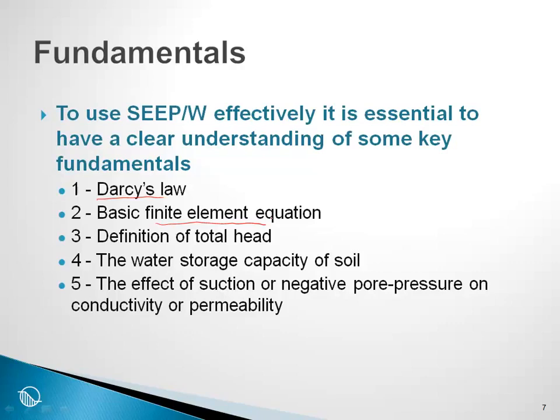It is absolutely mandatory to use SEEP-W that you have a clear understanding of the definition of the total head. We usually use big H for total head. Then we must have some idea about the soil's ability to store and release water. Soil acts a little bit like a sponge sometimes. It can absorb water, but water can also drain out of the soil. And the soil's ability to store water and to release water is fundamental to effective use of SEEP-W.